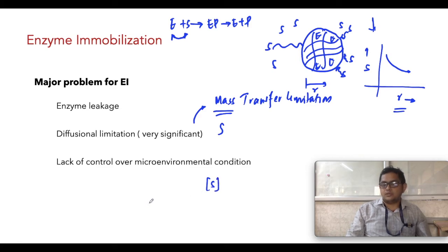You should know the residual substrate concentration in order to use those models. Here, you are unable to know the substrate concentration. Each point in the bead has a different substrate concentration. It creates a heterogeneous condition inside the beads. This heterogeneous condition definitely affects your prediction and productivity.